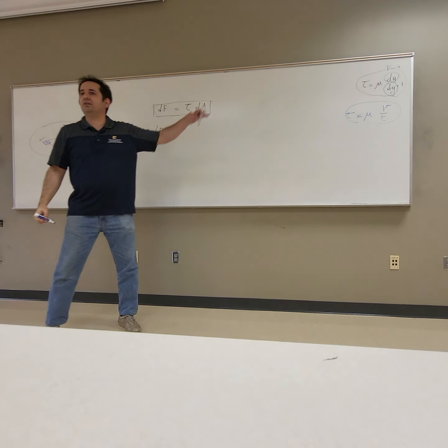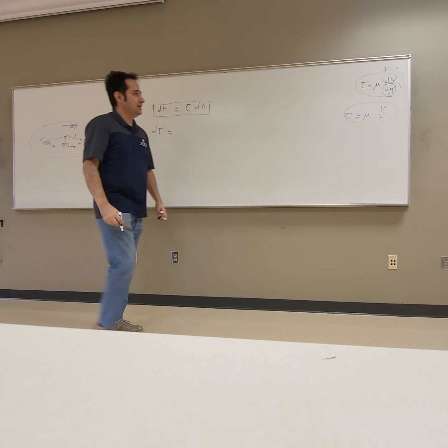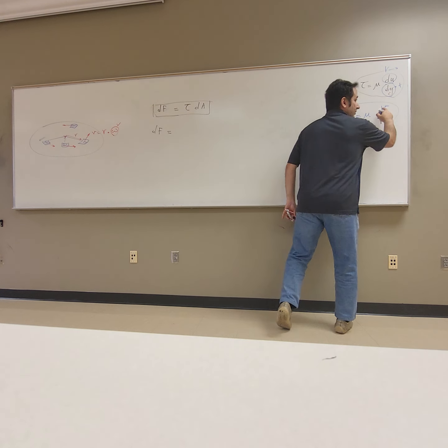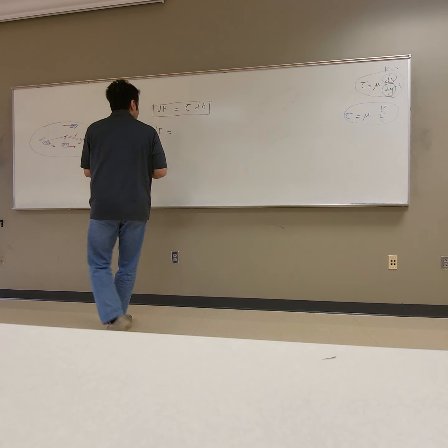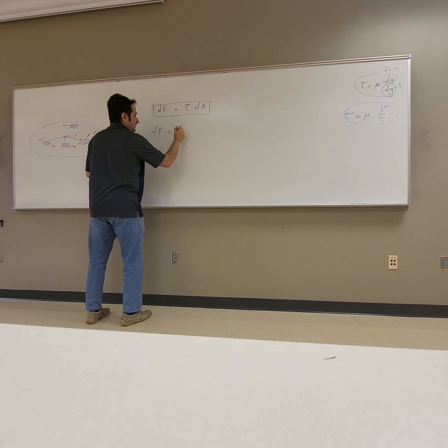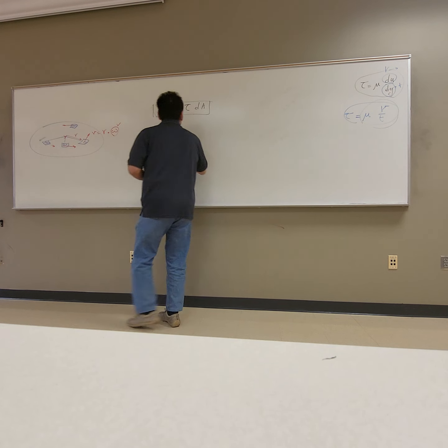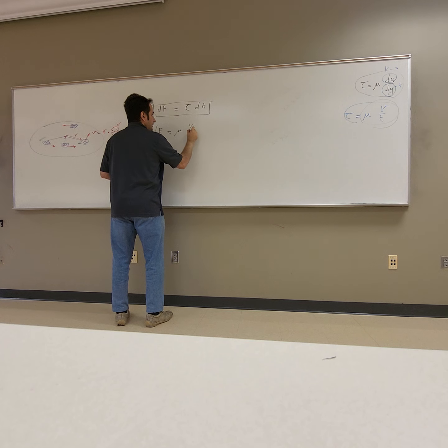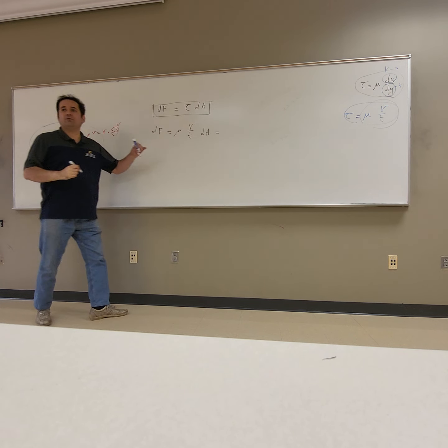But what is my velocity here? What should I put for velocity? R times omega, right? So you say dF is equal to tau dA, which tau is what? Mu V over T times dA is equal to, what should I put for V?